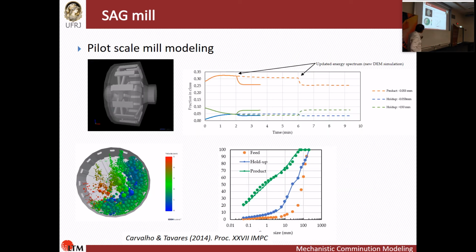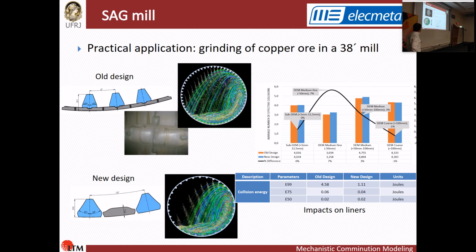So we did these different iterations, and we ended up being able to predict fairly well the holdup inside that mill as a function of the feed, and of course the product, assuming a given classification function. So it is still work in progress to do this properly in an industrial environment, but the idea is already there.